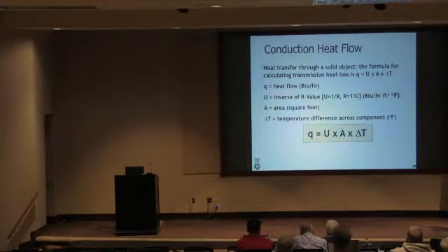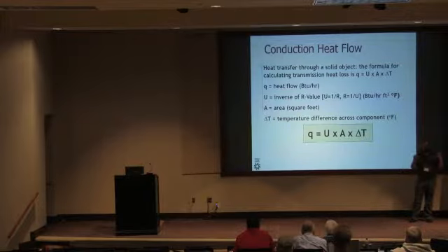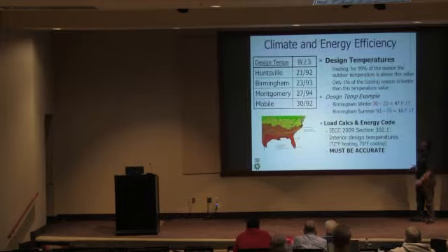It's back to that one installer, one pass, air seals and insulates in one product and reduces the operating temperature of the air around your HVAC system, versus trying to insulate on a flat ceiling and trying to make that a good solid air barrier, and then what's the operating temperature that your HVAC equipment is, and what's the delta T across that surface. So the reality of why spray foam really works is that it covers up so many of the problems that we have in the real world of trying to create that continuous air barrier and continuous insulation barrier in a home.